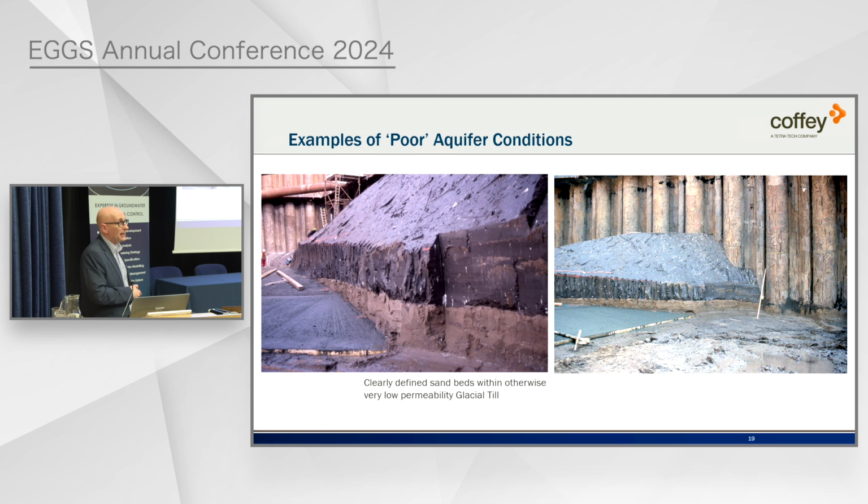And of course, this sand layer, which is water bearing, was in exactly the wrong position to help us with excavation, so it was in the right position to be very inconvenient. So we had to do some drainage measures there. But again, you see, this is something: is this an aquifer, is it an aquitard? How do we deal with it, how do we categorise it?